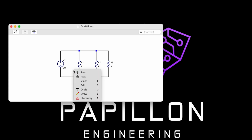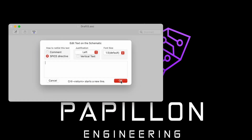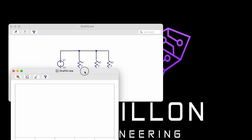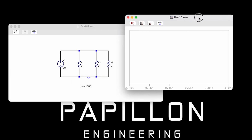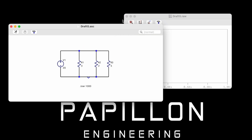And notice if you hit run immediately without including the SPICE directive, then it's not going to actually output anything. So don't forget to do that, 1,000 seconds. It doesn't have to be 1,000 seconds, but it's just convention to use that amount of time. And now you can run your circuit and now do the measurements for voltage and current.